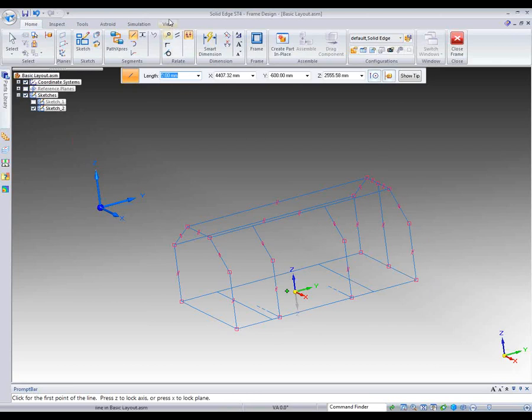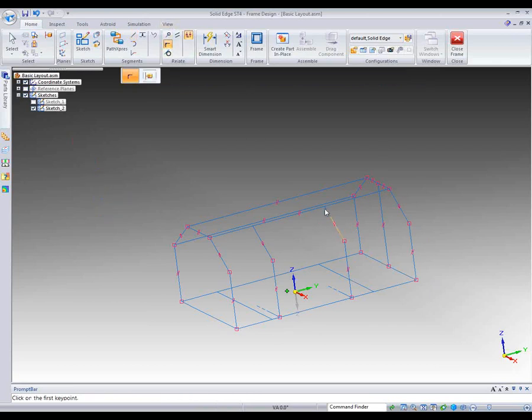Okay, one more thing that I want to do here, I want to make sure that the end of that is attached to there. You see a little connect icon appear, that's the little square box. The other ones, this means it's parallel to the X. This means the little plane there, that it's on the XY plane.